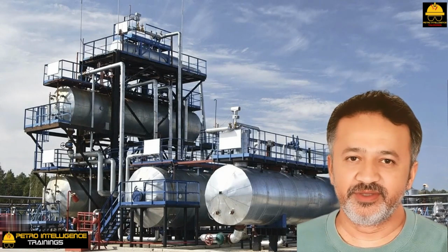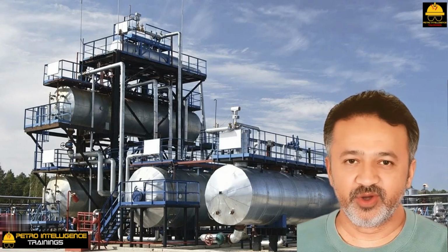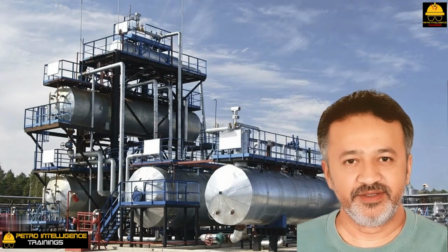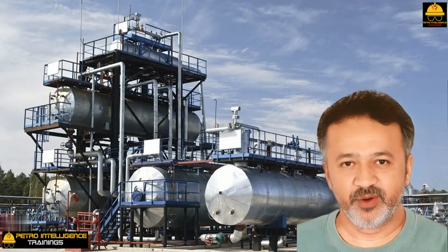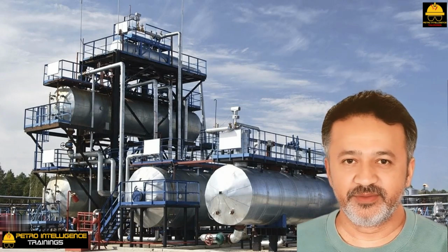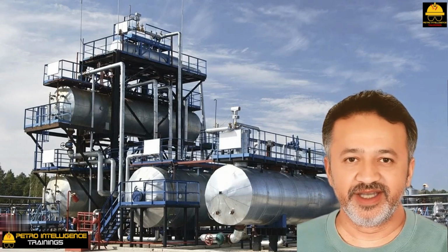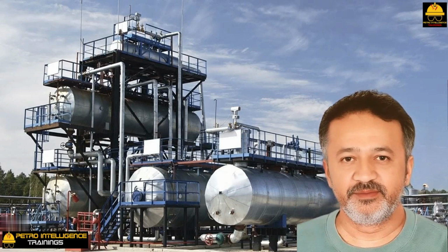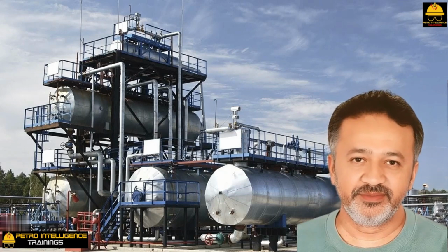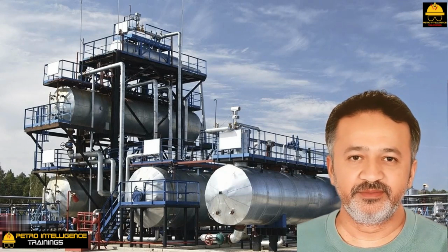When the steam condenses, the carbon dioxide may remain trapped in the reboiler or preheater as a non-condensable gas. Actually, there is no such thing as a non-condensable gas. Even CO2 is somewhat soluble in water. As the CO2 dissolves in the condensed steam, it forms carbonic acid, a relatively weak acid, pH typically between 5 and 6. Strong acids will have pH values of 1 to 2. Pure water has a pH of 7. Carbonic acid is corrosive to carbon steel heat exchanger tubes.